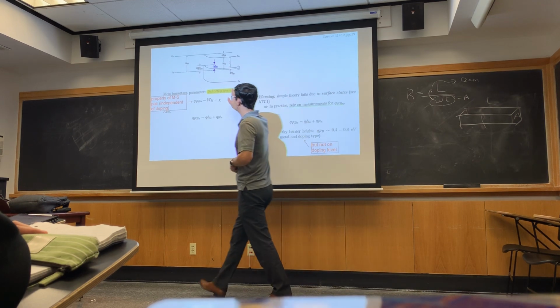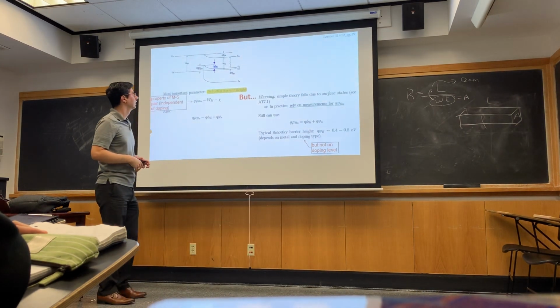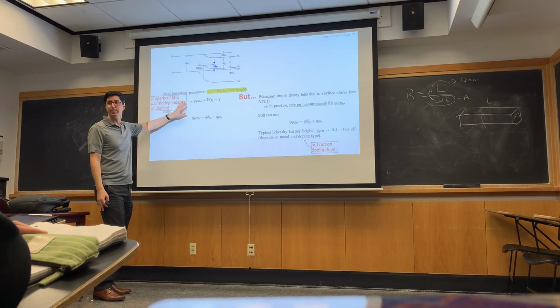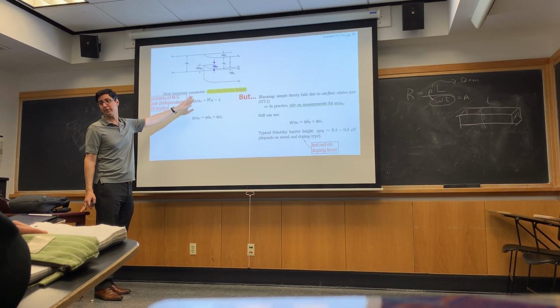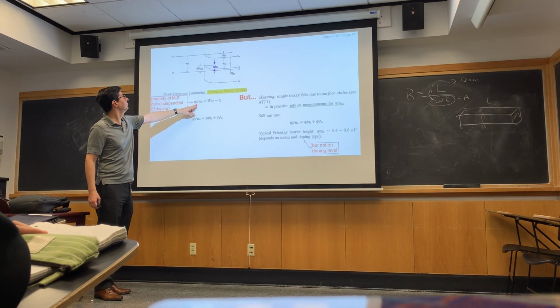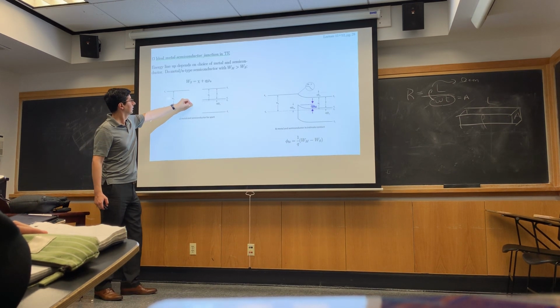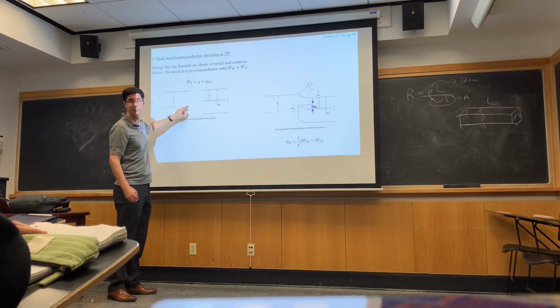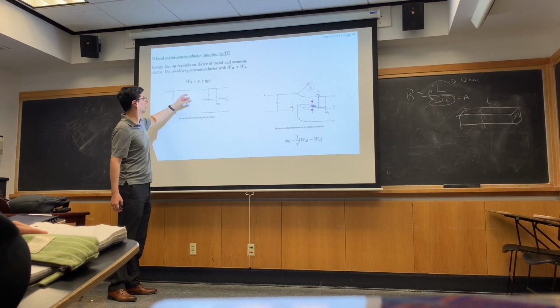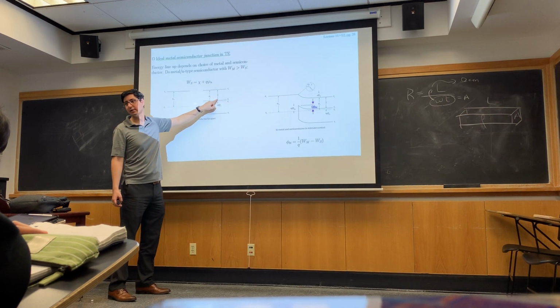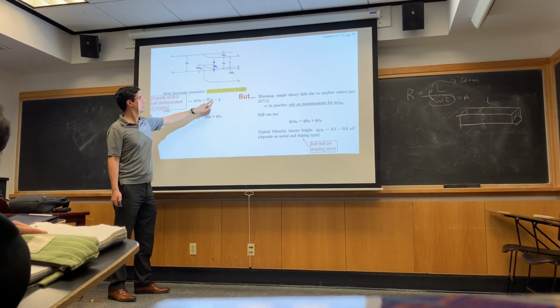Okay, so here's my band bending. And so this is this simple approximation. This is assuming a perfect junction. There's no non-idealities. And it just says that phi Bn is this, EC minus EF on the metal side before joining, which I can also express as the work function of the metal minus chi of the semiconductor.